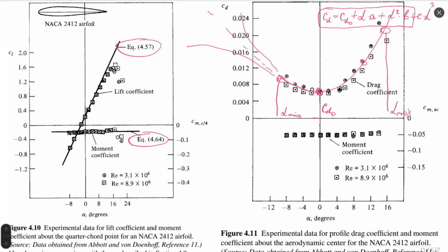It's predicted. It's not something unknown. So I recommend you to use it in the middle. And this is especially for drag coefficient. For other coefficients, for example, moment coefficients, this is not applied. Not applied, because depending on Reynolds number and angle of attack, you can find completely different behavior of momentum coefficients.